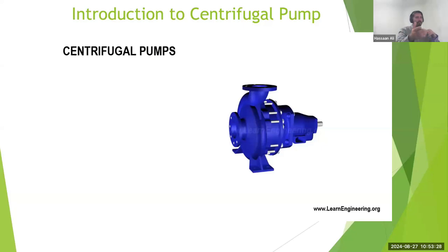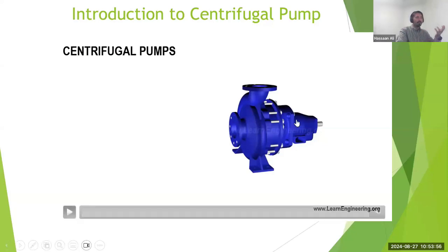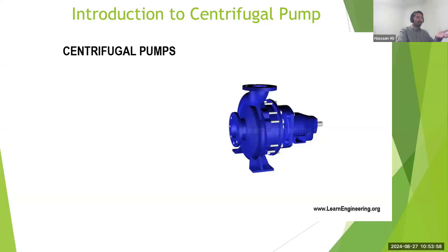Now that is exactly the same principle that is used in horizontal pumping systems in the oil field, where you have these ESP barrels, which is an electrical submersible pump barrel with multiple impellers all stacked into each other. And the way they are stacked is that the discharge of one impeller goes to the suction of the second impeller, and the discharge of the second impeller goes to the suction of the third impeller. And that's how you will increase your pressure. For the water flood applications, you cannot use a simple one-stage pump. You have to use a multi-stage pump.